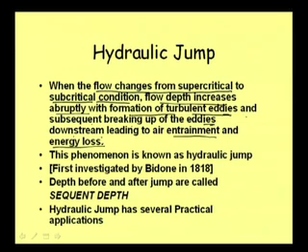Well, so as far as the definition of hydraulic jump is concerned, when the flow changes from supercritical to subcritical, the flow depth changes abruptly with a lot of turbulence, with air entrainment into it, and which is associated with loss of energy. This flow phenomenon is known as hydraulic jump. And of course, the first investigation of this phenomenon was carried out by Bidone, in 1818, long back. Even today, although it was investigated long back, this phenomenon is interesting and people are working on it to know more about it.